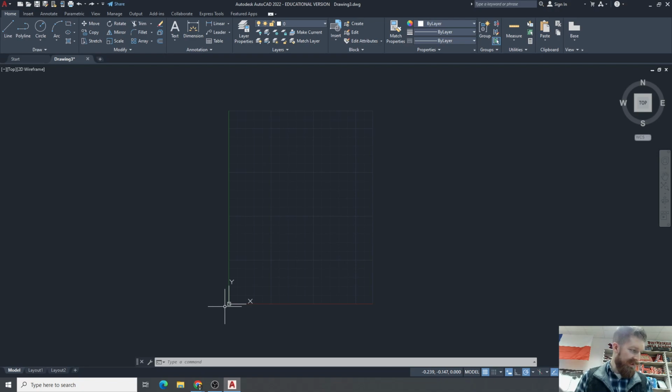So for example, if I'm going to print on this 8.5 by 11 sheet of paper, and I draw on this 8.5 by 11 limits workspace, then my DSF, my scale factor, is 1, like we just mentioned.